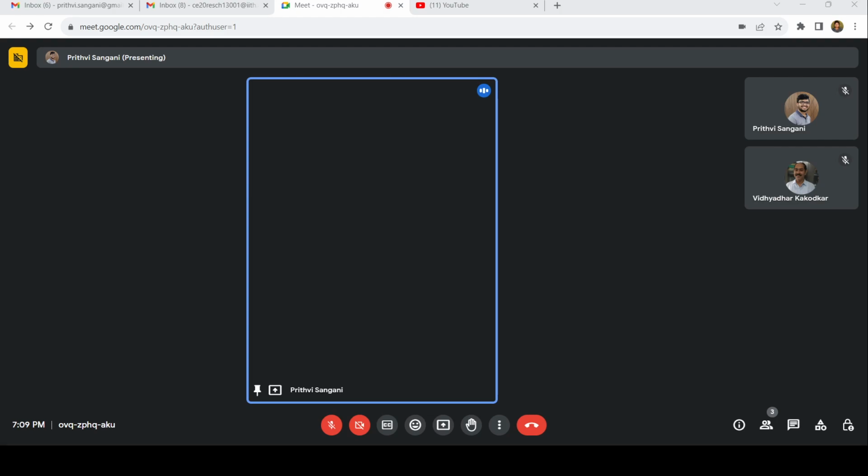Yeah, we were following delta 1, right? So I'll take this as delta 1. Again, to find delta 1 itself is a problem. To find delta 1, we'll apply a unit force in that direction, find the internal forces in the members, and then use delta = sigma FUL by AE. So this is one part, and what is the next part?